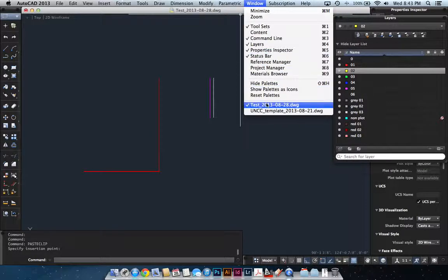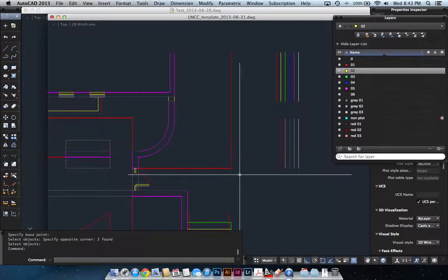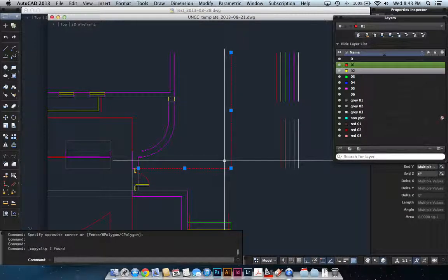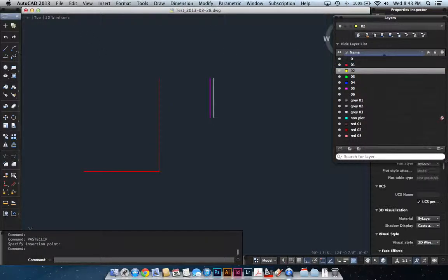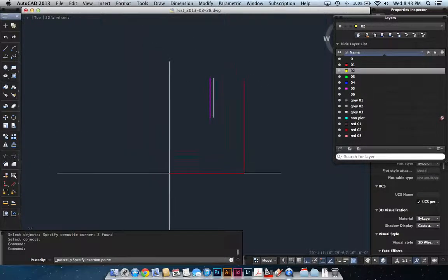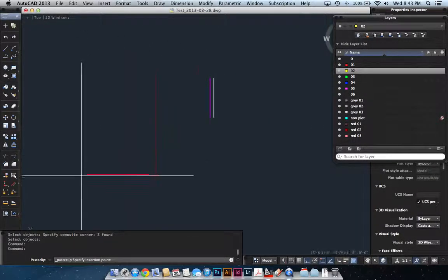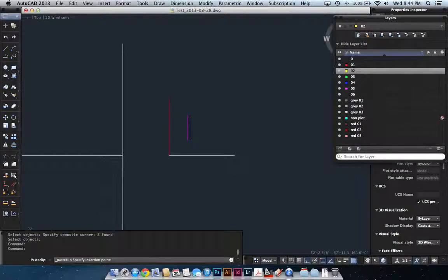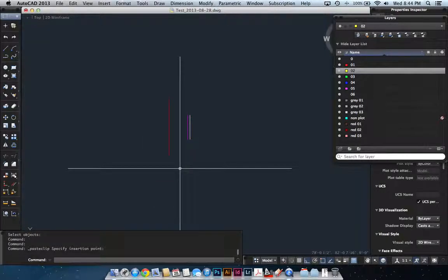in the other drawing. The other option, which people have been talking around in Studio, is just by selecting the object and Command C, copy like it is in other programs, and then coming into this drawing, what I'll do is I'll first erase these lines, and then Command V, I now have this object. I don't have it now smartly located, but if you're just trying to bring data in, bring other line work into a certain drawing, you can just Command C and then Command V, and then it just wants to specify that insertion point. And now I've located that element.